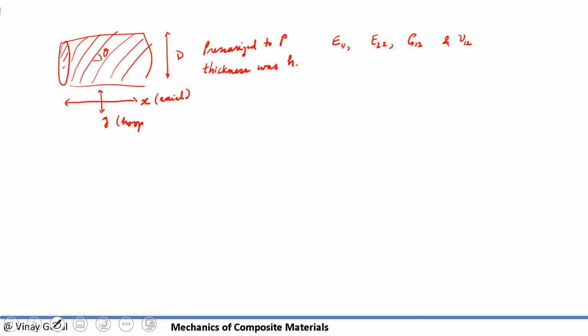axial, then sigma XX equals the pressure inside the vessel times D, the diameter, divided by 4H. That's the axial stress. And the hoop stress is PD divided by 2H. And that comes from formulas from books on mechanics of materials. So you can calculate that. If the pressure is given to you, the thickness, and the diameter was given to you, I can calculate these stresses fairly simply.